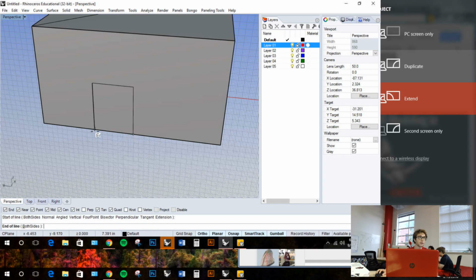Is there any way to make sure that your lines are 90 degrees to the line? So one setting that I have turned on right here is Ortho. This is just orthogonal. So without it, if I draw a line, it's going to be all over the place. You still get a guide sometimes, but Ortho makes things a bit easier. It's essentially trying to lock you into an orthogonal direction when you draw a line. If you don't want to have orthogonality, you can hold Shift while you're moving this around if you have the orthogonal setting on. It's down here at the bottom.